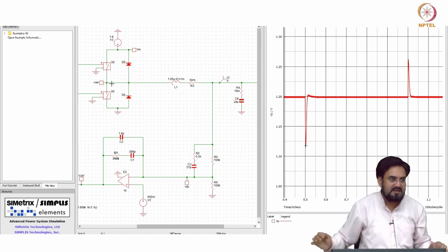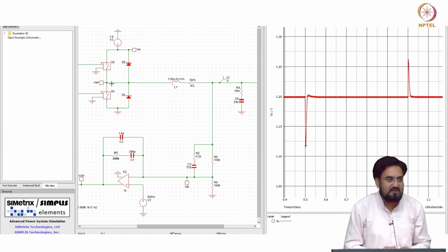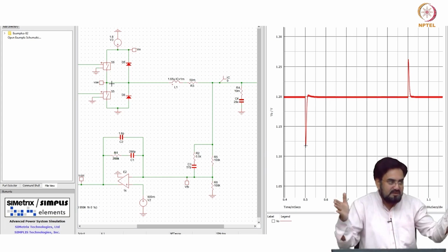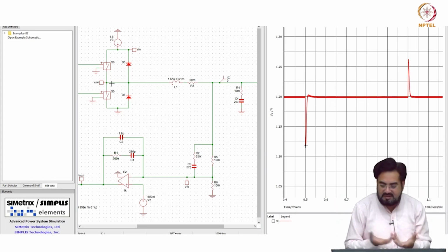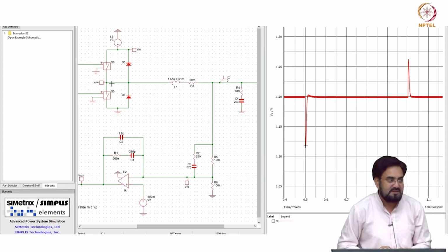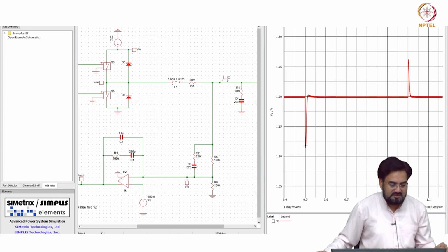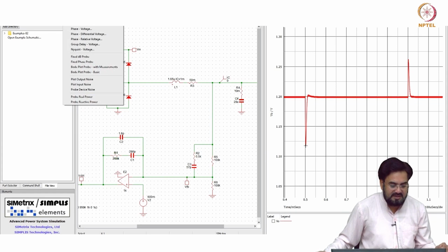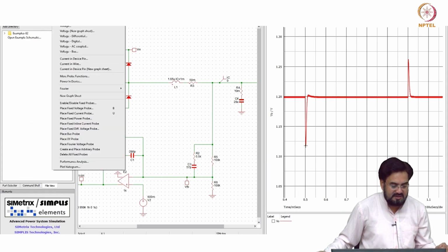Now you are widening that band. Overall, the loop gain will also flatten out for a wider range. That will not look like a first order system in that case. So settling will not be good in that case, and we can look here.